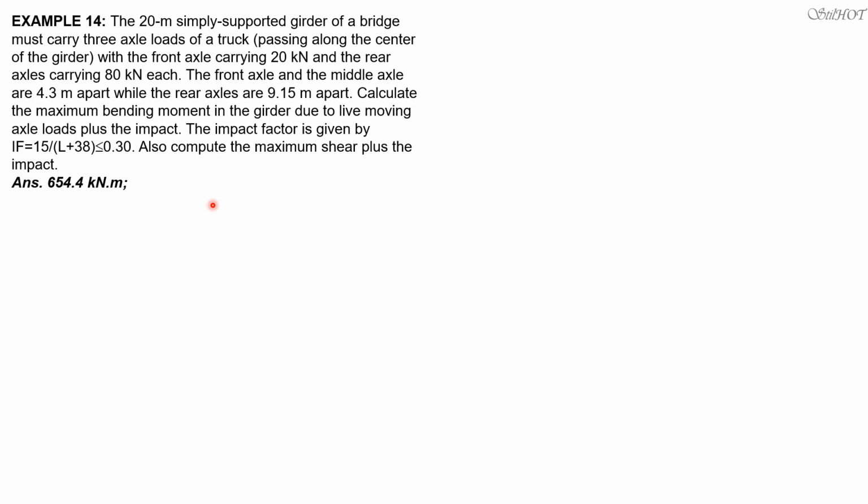The impact factor is given by 15 over L plus 38 and should be less than or equal to 0.3. Also compute the maximum shear plus the impact. So first, let's position the loads to cause maximum moment, and we observe the position of the loadings.